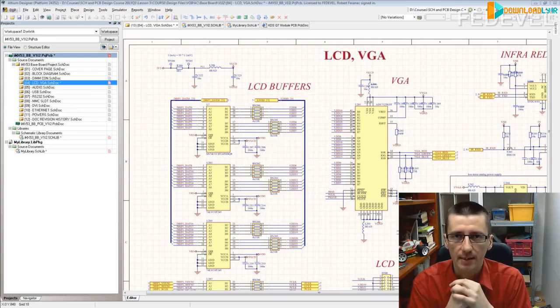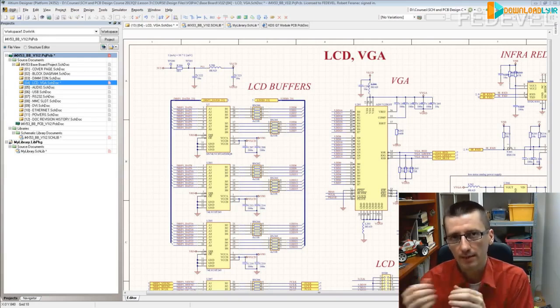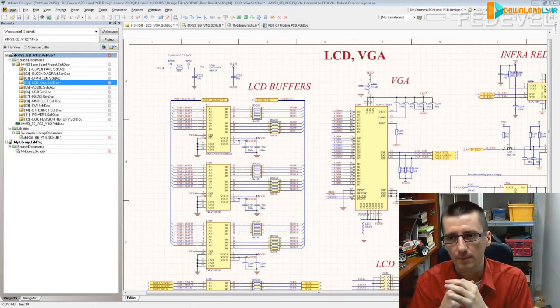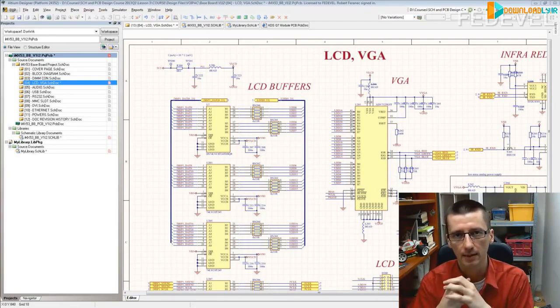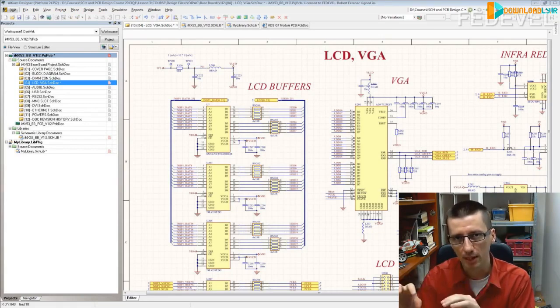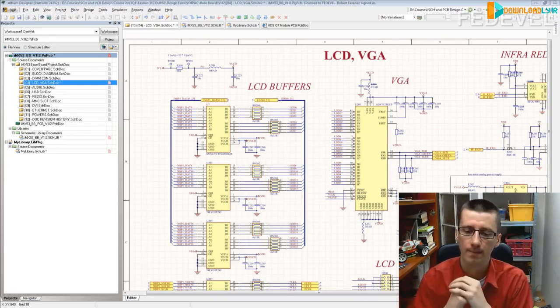we had an ESD issue. The design guide said place a bead, a ferrite, on the ground and on the power. And when the device was tested by the ESD gun, the pulse didn't discharge through the ferrite, but it discharged inside the chip. So it damaged the chip. When we replaced the ferrites with a 0 ohm resistor, everything worked okay.